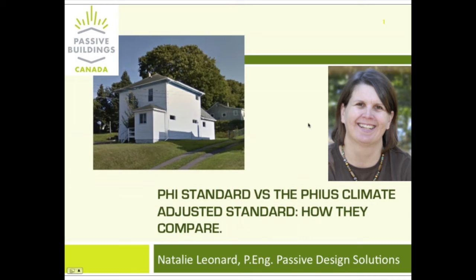I think the final air tightness was like 0.43 on that project, so that helps quite a bit. And second, because it's quite high density, so it's 4 occupants in a relatively small building, our energy budget was quite good. So we just had electric heat and a hot water heat pump, Energy Star appliances, nothing really special on the appliances, and we reached the PE.